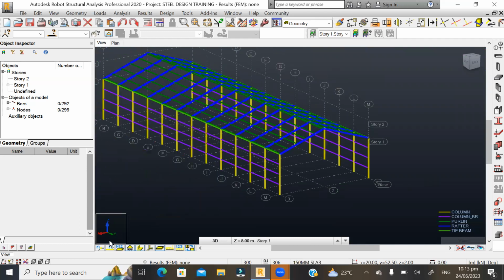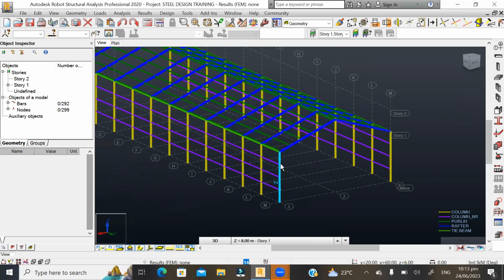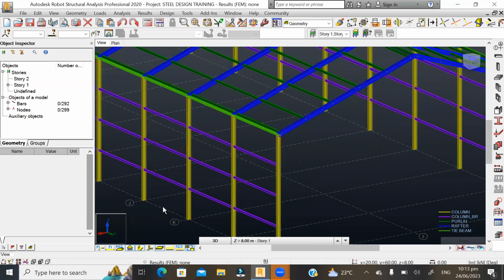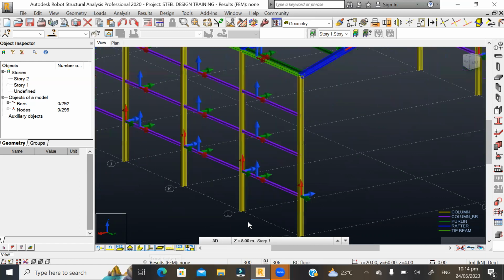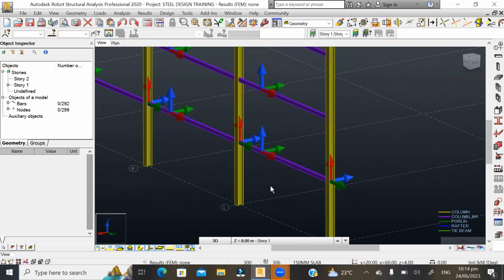All right. Then another thing I want us to do, which is very, very important for our analysis. Look at these coordinates, this Z, X, and Y coordinates. Your Z coordinates for each of these sections must always be outside your model. To bring out the coordinate for each of the members, you can click on this local system that you have here. When you click on it, you can see the coordinates for each member.